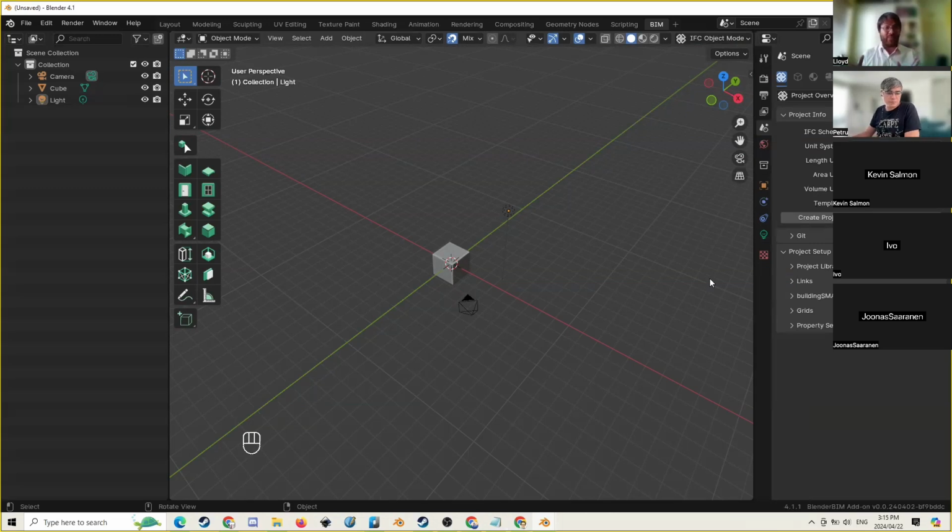All right, so here we're going to create our IFC file. I'm going to be using IFC4. I'd recommend that if you're going to do any sort of native IFC modeling. I'm going to be using metric, millimeters, square, and cube meters. And then for the templates, I would say you need to start with the IFC4 demo template. So this will have everything we need in it already.